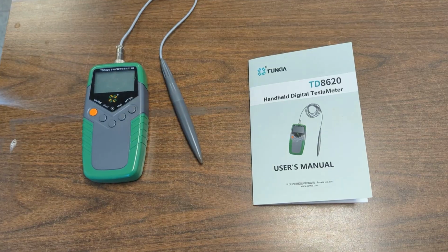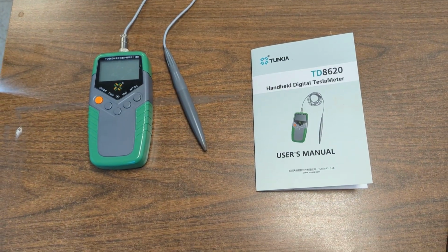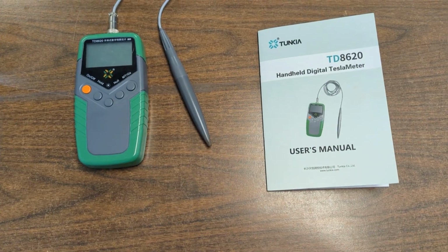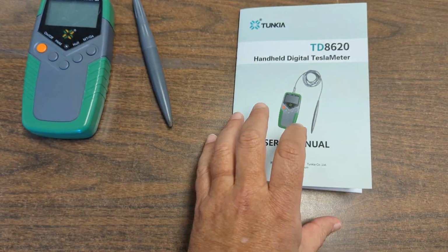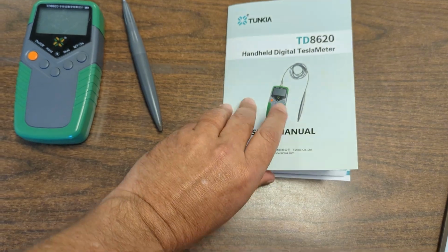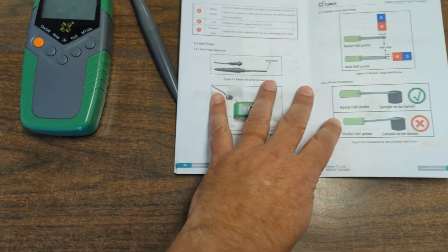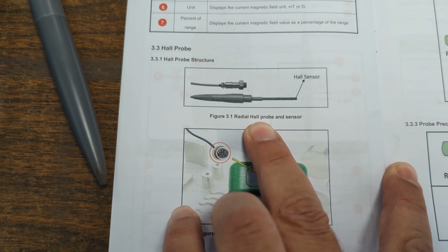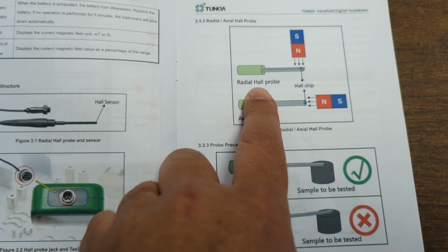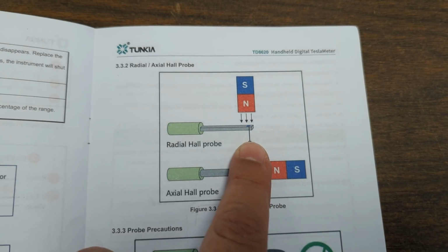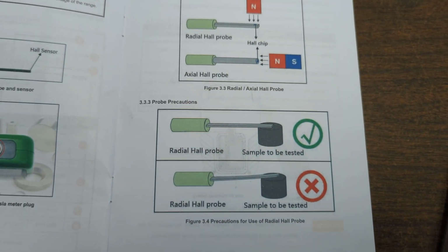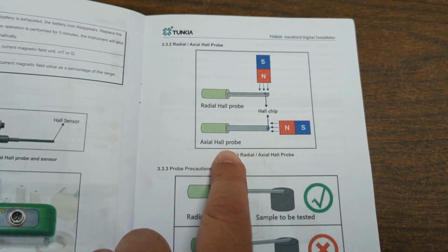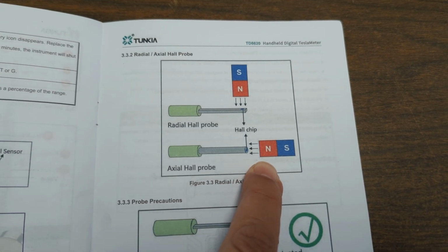The instrument I'll be using to do the residual shaft magnetism measurement is called a Gauss meter or Tesla meter. This is commercially available. This is just one of the units. One thing I need to check is that this one specifically has got a radial probe, and it shows you here for a radial probe this is how you do the measurements. You can't do it this way. If you have an axial probe, you need to do your measurement like this.